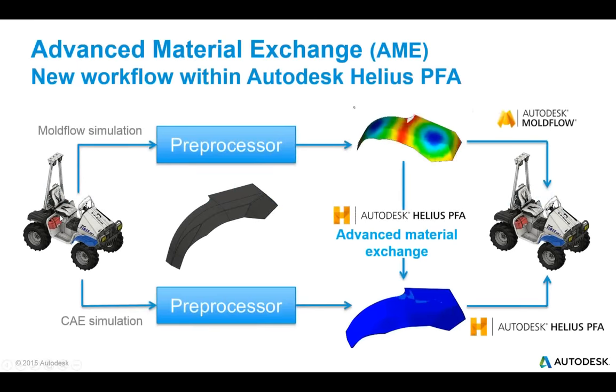As I mentioned, advanced material exchange maps data from mold flow to structural simulation. And we typically see there are two different groups that are running these simulations. One is performing the manufacturing simulation, which is the mold flow simulation. The other is performing the structural simulation in Abaqus or ANSYS or Nastran or what have you. But there's usually a disconnect between those two groups. On the structural side, we usually are using isotropic assumed material properties, and we're not taking into account any fiber orientations or any residual strains contributing to warp. So it's kind of either a gross over or underestimation of the material response.